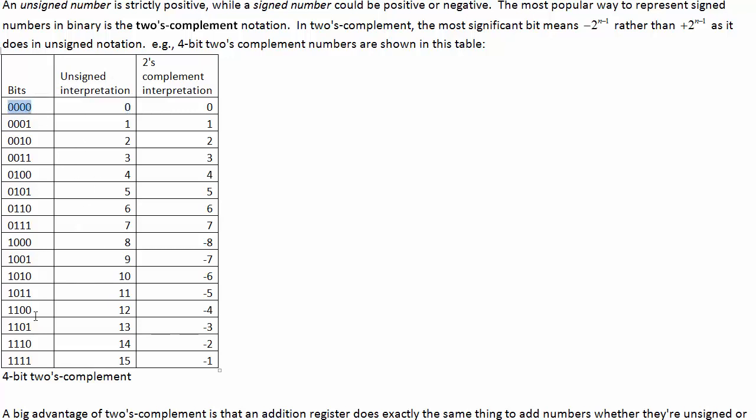Now, in signed numbers, in 2's complement, let's look at what it says. It says -1 plus 1 is 0. Well, that's right. There's nothing wrong with that. So the overflow didn't happen in that spot.